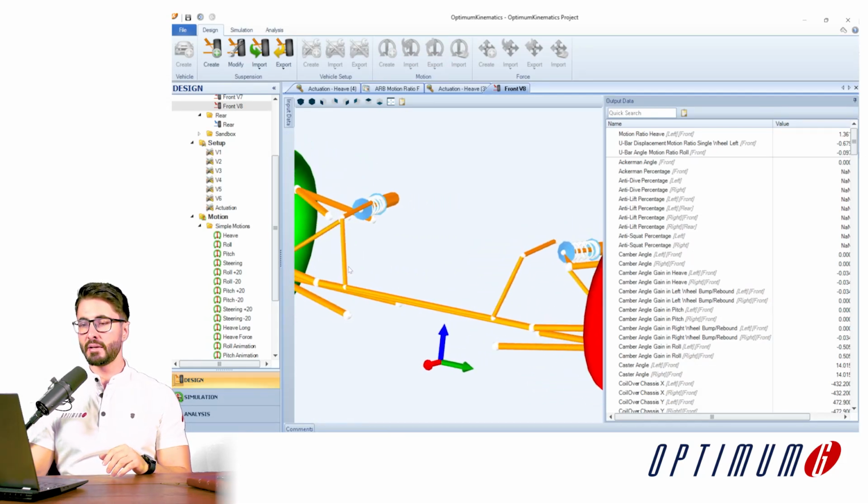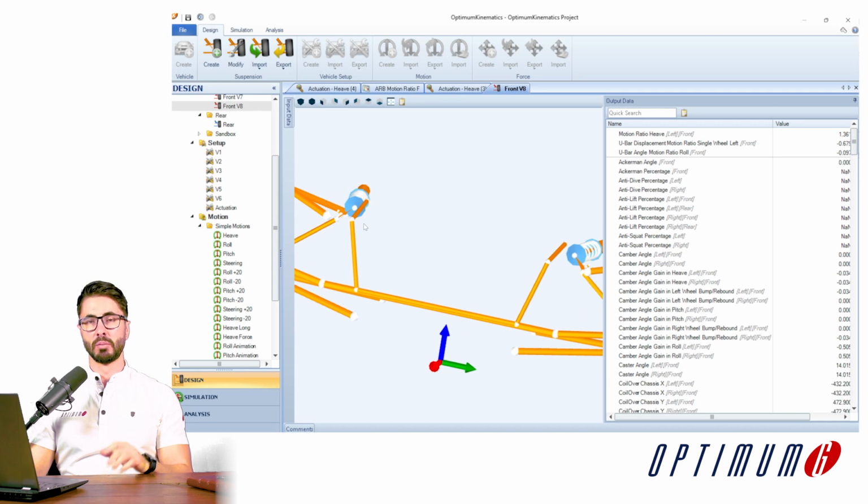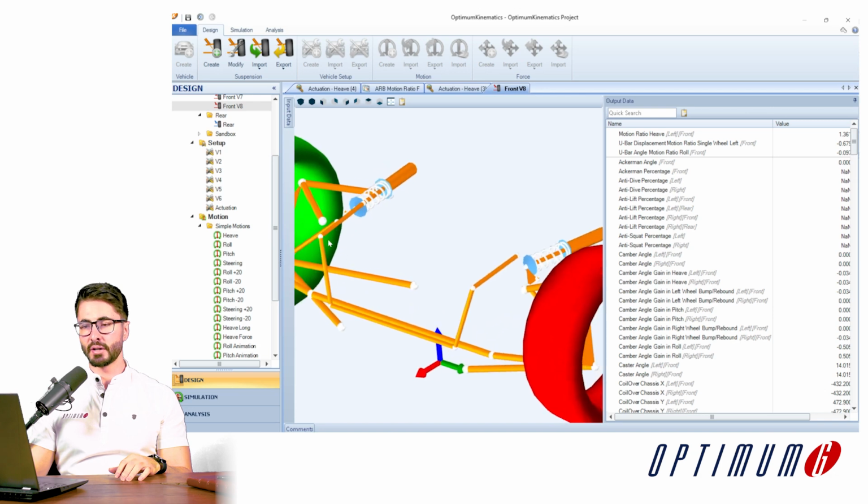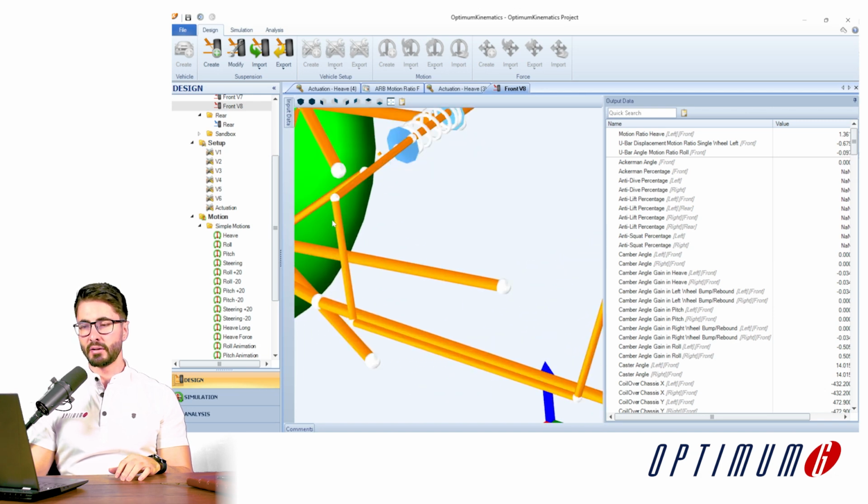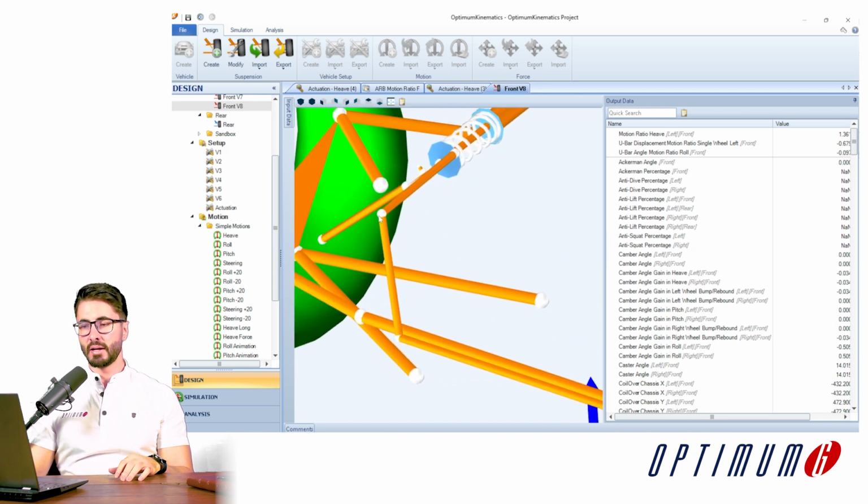In this example, we could have different options. We could have the blade being a flexible blade where you just adjust the angle and it changes the stiffness of the component. Or what we're going to use for this case, since it's just a little simpler, we're going to define different pickup points over here. So when we look at the blade, we would have different attachment points a little further away or a little closer to the entry bar, and this will change the stiffness of the system.